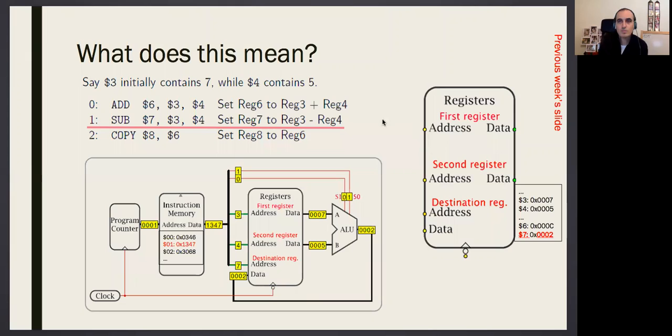Okay, so what does that mean? You remember the slides from the previous week. We had these machine codes, and I had this in the instruction memory. You remember this? Instruction memory. So when I had this line here, because of the connections, because this hex nibble is 1, and 2 bits of that nibble were connected to the ALU, which made the ALU do the subtraction operation. That's why this 1 here means subtraction. Which operands? Well, register 3 and 4 because of these nibbles. When 3 is connected to here, register 3 will be outputting data from this line.